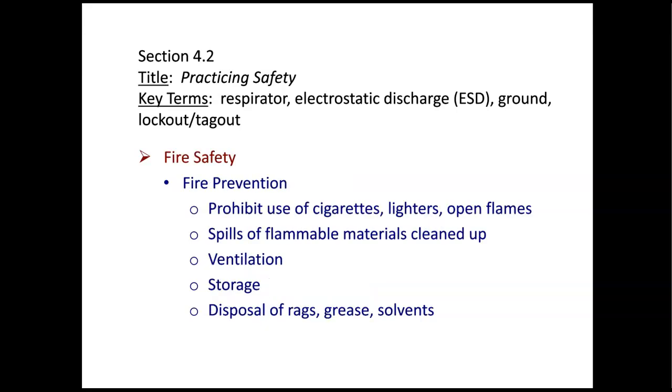Fire safety and fire prevention is important. A lot of companies will prohibit the use of cigarettes, lighters, and open flames. They might only allow those in certain areas, if allowed at all. Spills of flammable materials need to be cleaned up right away. Obviously ventilation is important, as is storage and the disposal of rags, grease, and solvents, to help prevent fires from occurring on the factory and shop floor.